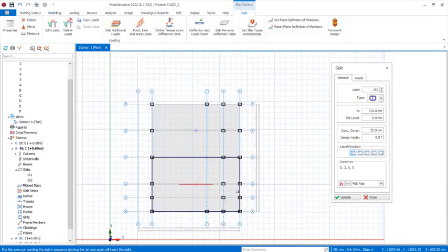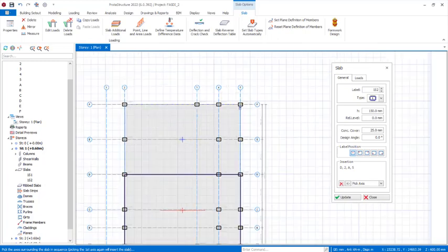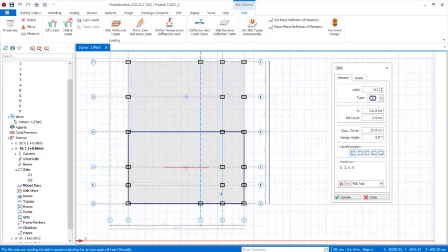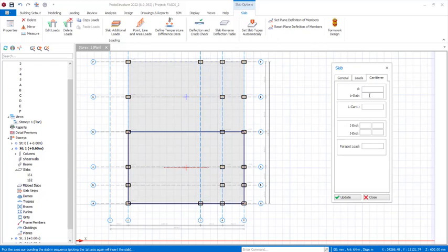Now this time around we are going to be inserting another slab, so that we can have a very nice walkway around this structure. For us to do that, we right click in these provisions. We are going to be using slab option 12, this one. So click on that, come to this provisions. It's going to be a kind of cantilever slab right there. For the length of the cantilever, we will be considering 1500, just like this.